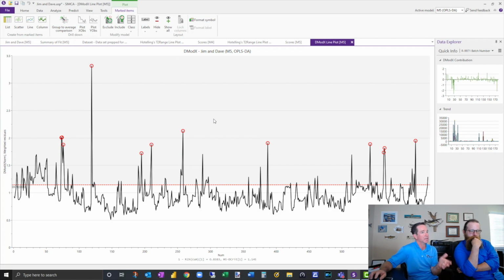A good data scientist looks at a lot of this stuff, but here's where the data scientist doesn't necessarily understand. What is that co-feed flow? What is that wait time? They don't really know. Since a lot of us have been controls engineers, we've been around plants, we can say that's probably an outlier. If it sat and waited for very long, or the temperature was really high compared to normal, that's probably not going to be a good one for us. So we'll go ahead and exclude some through the DModX process as well.